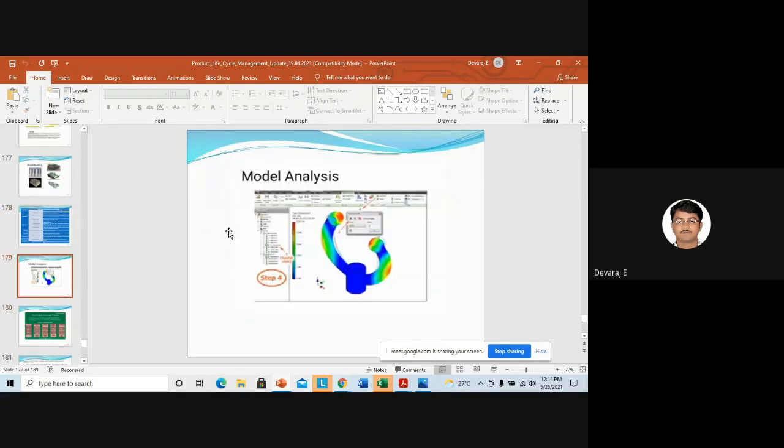What is model analysis? Can anyone tell me? So you're testing it with respect to various criteria, sir. Like, assume for stress, you set the limit, you check the concentration at different regions, and you see whether it is meeting the parameters required for the product usage. And then you check with respect to temperature, how temperature will affect the material property, and whether this material should be selected or some other material should be taken for the same application. Good, Sachin.